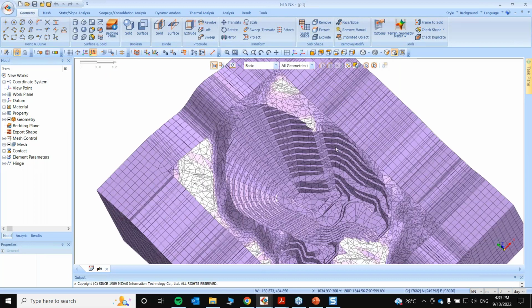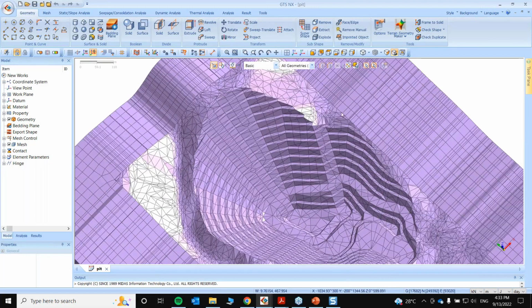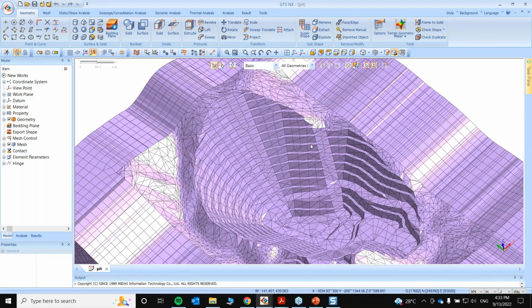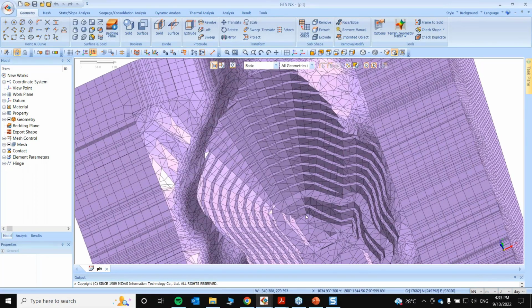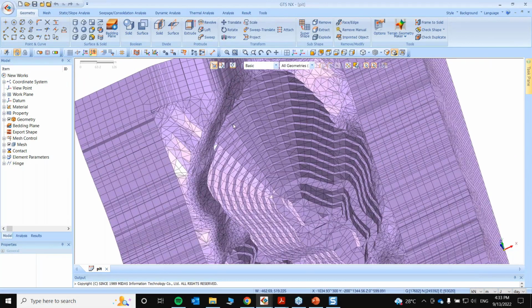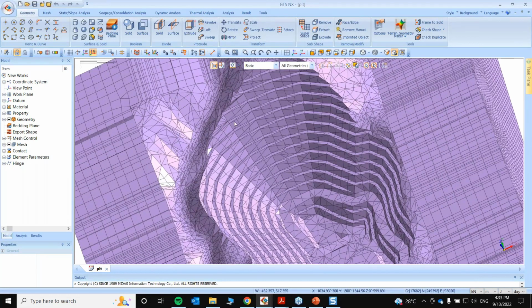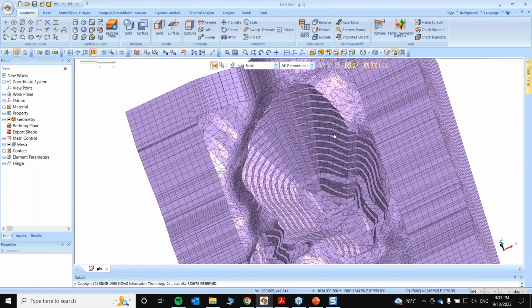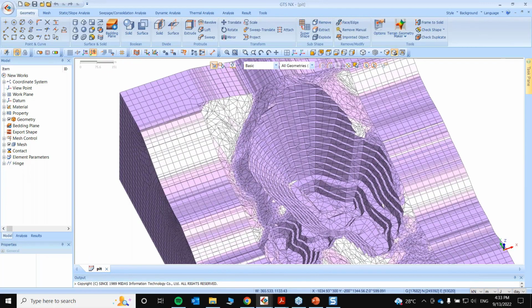Some faces are convex shaped too, depending on the rock stiffness in that area. But if you watch closely, the ultimate pit angle at each point from the toe to the top is constant. That has to be maintained. Your ultimate pit slope angle will be constant, but your local pit slope angle is variable depending on the progression of the mining. And the final pit slope angle can obviously be determined with the FOS value.